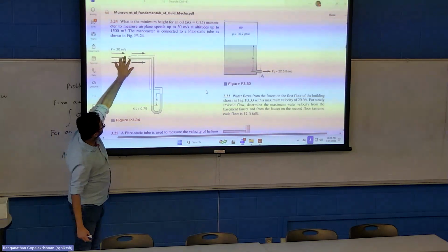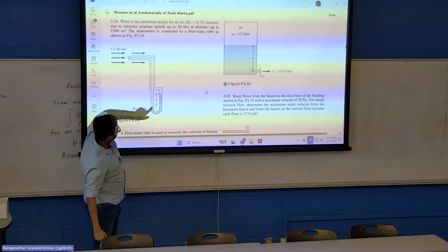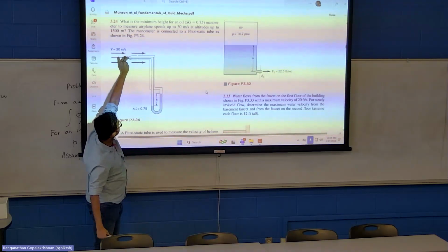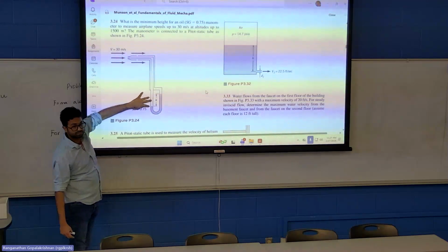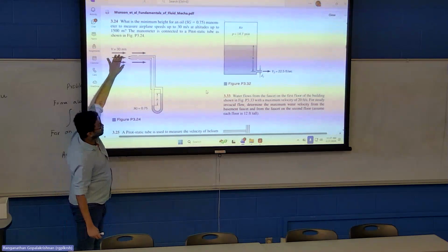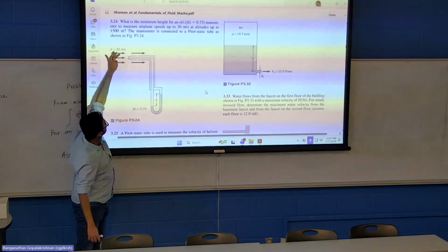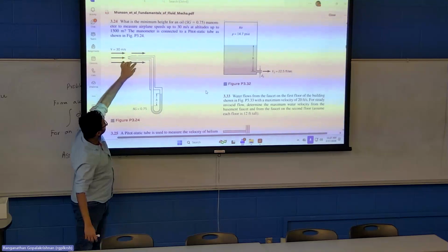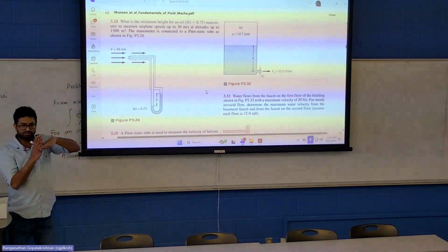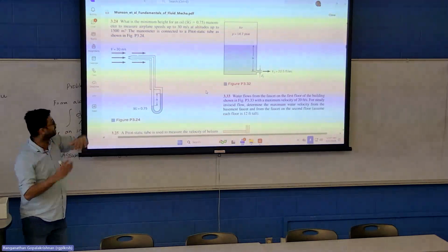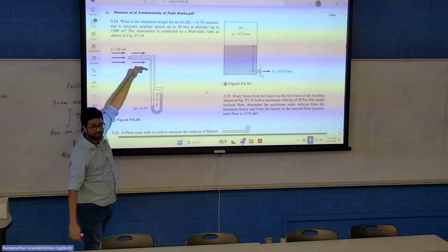Some of the air goes through the inner tube, where it just takes a turn and is decelerated by the liquid here. That is, the assumption is the air is brought to rest from 30 meters per second to 0. Another fraction of the air which doesn't go through the inner tube continues to travel past the outer tube, and you can see these two holes that are drilled 90 degrees to the airflow. These holes are drilled such that they are perpendicular to the airflow direction.